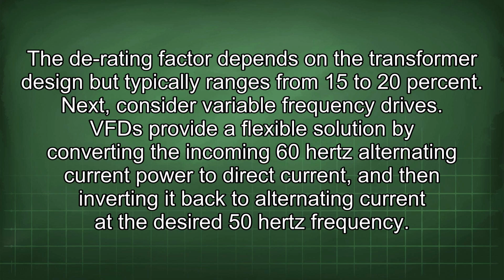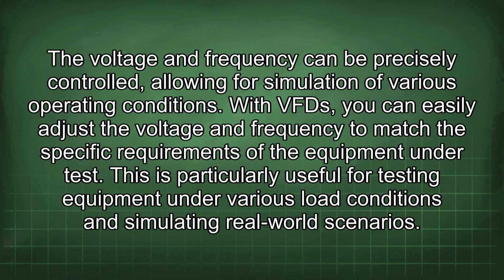Next, consider variable frequency drives. VFD provide a flexible solution by converting the incoming 60 Hz alternating current power to direct current, and then inverting it back to alternating current at the desired 50 Hz frequency. The voltage and frequency can be precisely controlled, allowing for simulation of various operating conditions. With VFD, you can easily adjust the voltage and frequency to match the specific requirements of the equipment under test. This is particularly useful for testing equipment under various load conditions and simulating real-world scenarios.